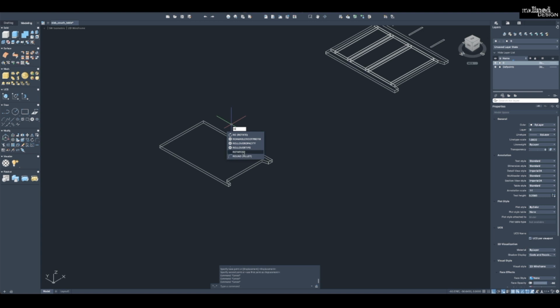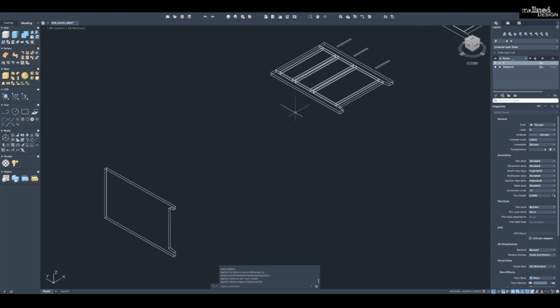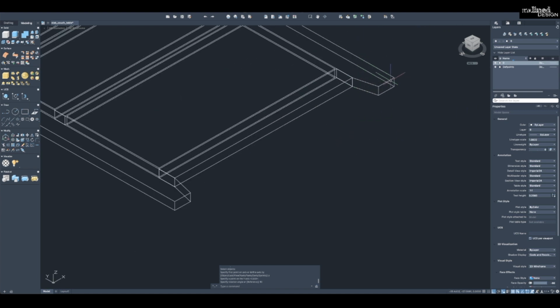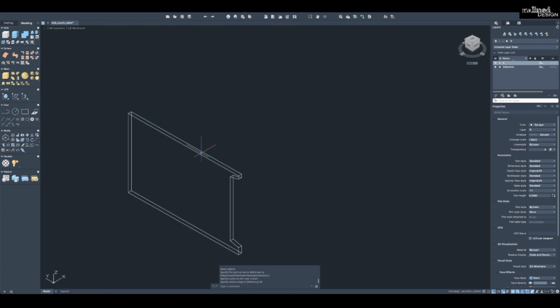I got my rotate 3D. You can also use the rotate, I'll have to look it up, 3D something, and it gives you the arrows like a gimbal on it that you can rotate it. So I'm going to select my object. And I'm going to rotate it on the Y by 90 degrees. That causes it to rotate down. And then one thing I'm going to do is, because if we actually build this, we'll be mitering that actual wood leg to the plywood side.